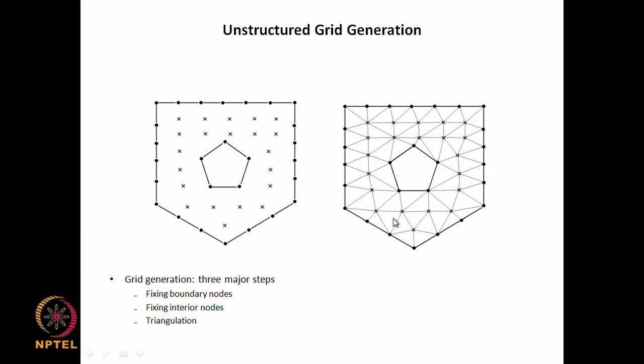Now, this is a very coarse grid, and we really cannot use it for CFD solutions with any kind of accuracy, but the idea is to go from there to here, where we have a grid which meets those considerations: all the boundaries are part of this grid, the whole boundary is there, and all the computational domain is included as the area of the individual cells, and the sum of the areas of all the triangular cells is equal to the area of the computational domain.